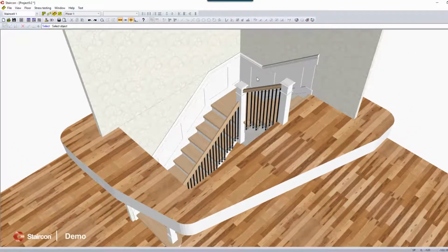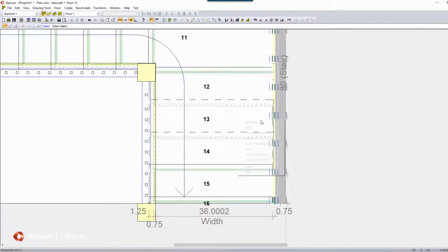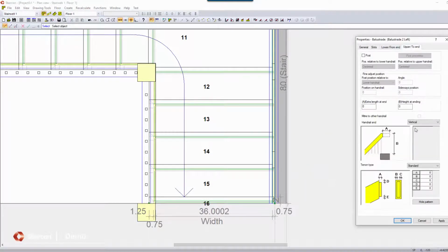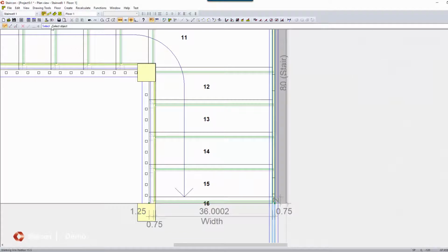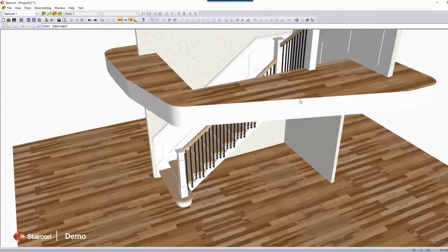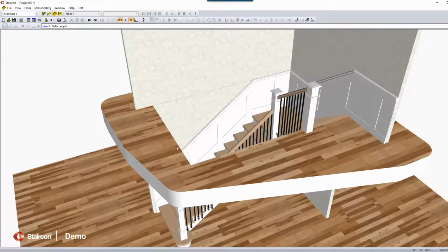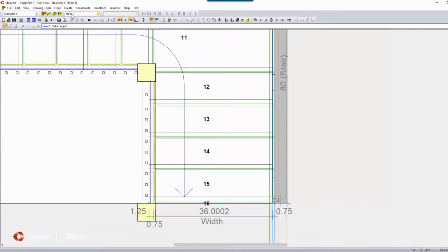So here we see a piece of wall that doesn't have anything yet, so we can just lengthen it out. Going to the properties of this balustrade, and to the upper end we can say the height and the length. So in this case the height at ending 38 and then an extra length of 40, because I know that I made an extra wall of 40 inches long. So now that's done as well. So basically balustrades on the floor is what's left.